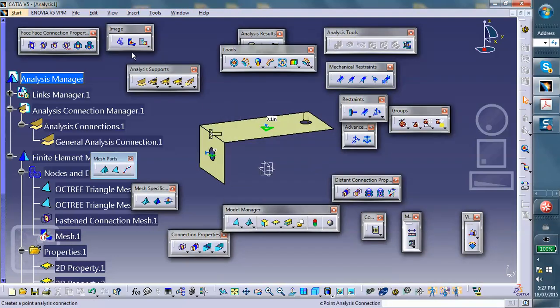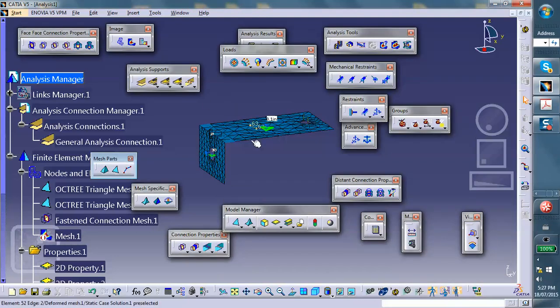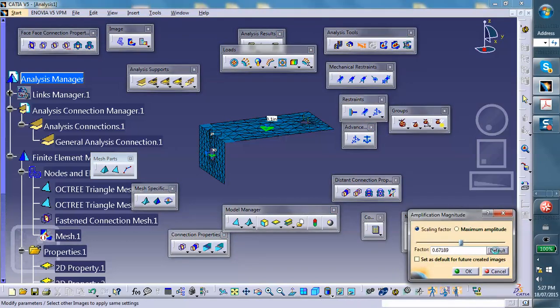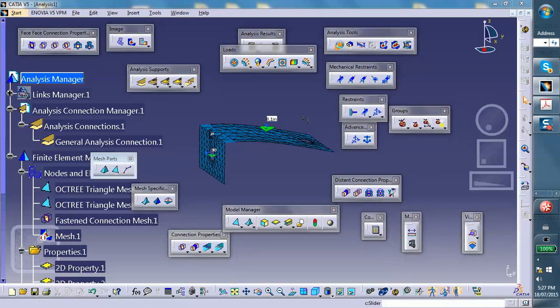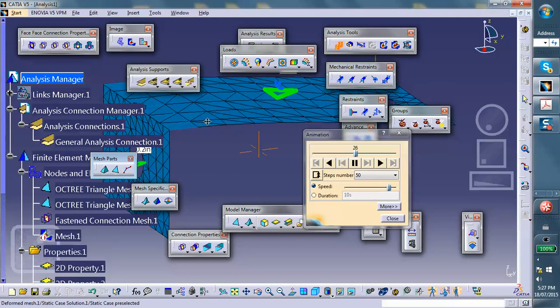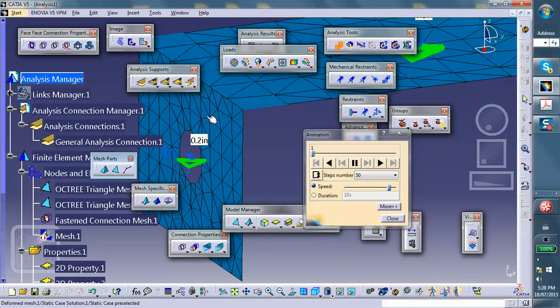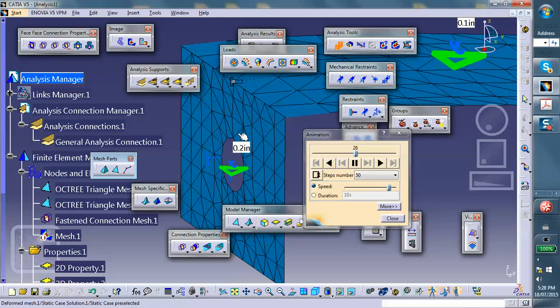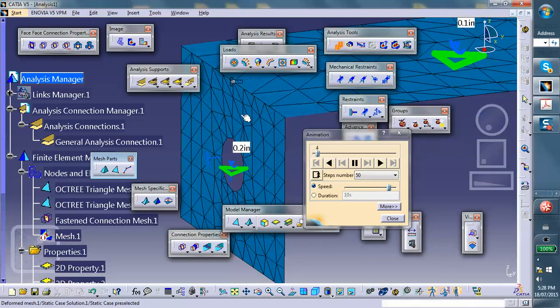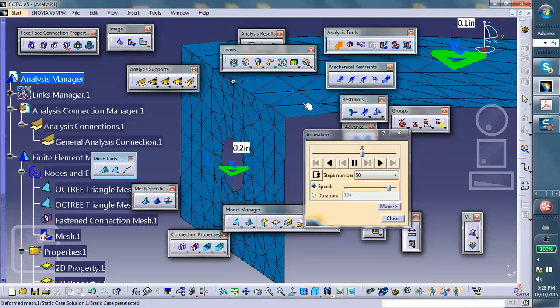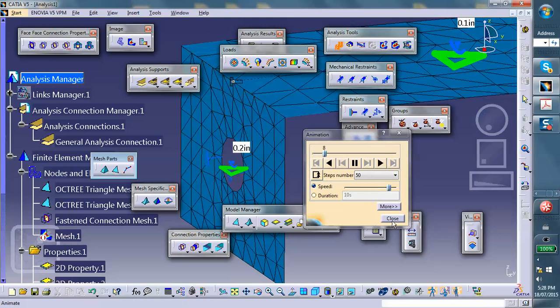And it will work. So if you look at the deflection, notice that it tries to show you deflection, except that the scale was changed. So let's put it on the default, and you can see that it's actually deflecting. There is also deformation in the vertical face, but it is so much smaller compared to the horizontal face that you can't even see it, okay?